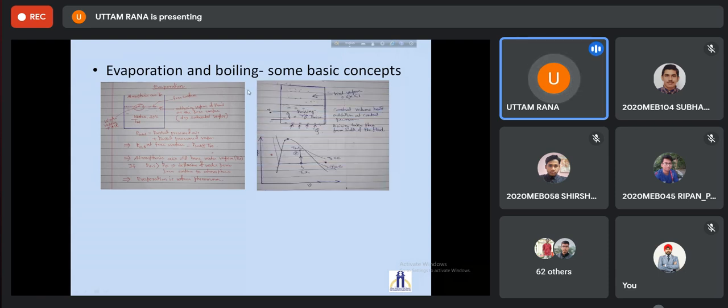When I talk about a boiling phenomenon, boiling takes place throughout the media, and during boiling the temperature is higher than the saturation temperature, or T is greater than the boiling point temperature. Here you can see water bubbles form in vapors, and as they are collected, they entrain some amount of water into the vapor. So if you consider a closed container and boil some water, whatever is collected at the top is a wet vapor.